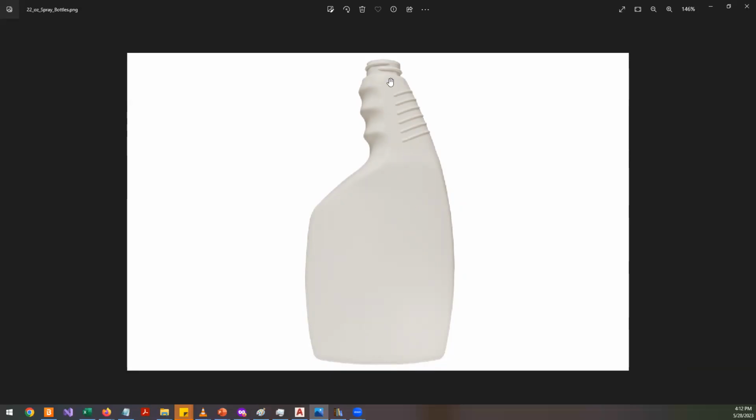The important thing that you have to notice is that the cross section changes from top to bottom. If you have something like that, remember you can't model this one with a revolve command. You will not be able to find an axis or a suitable cross section to use for the revolve command. No, it can't be used. Extrude definitely you can't use.